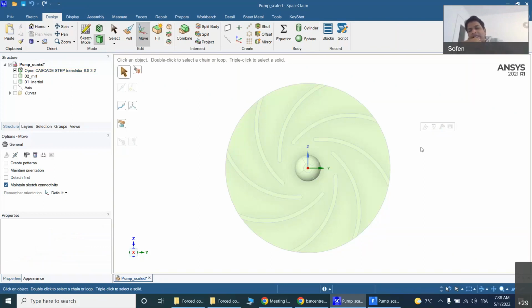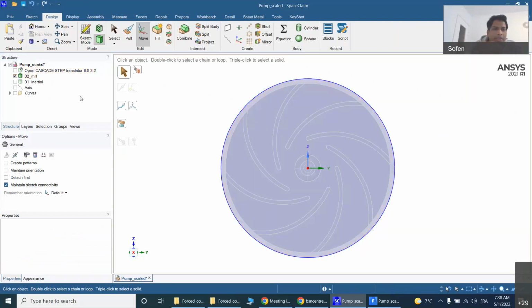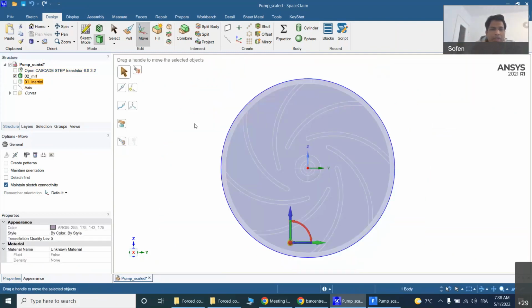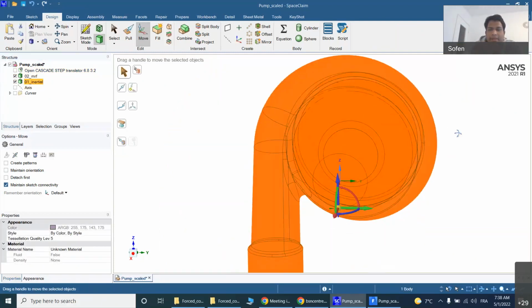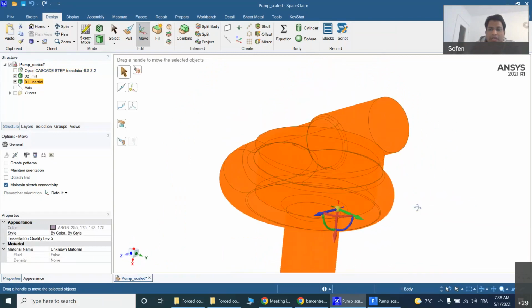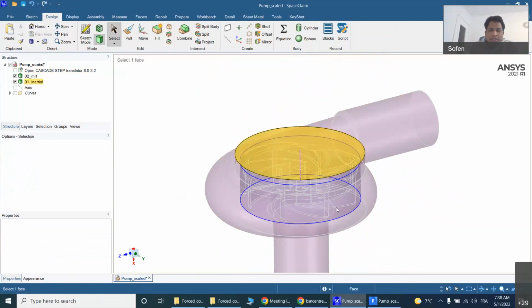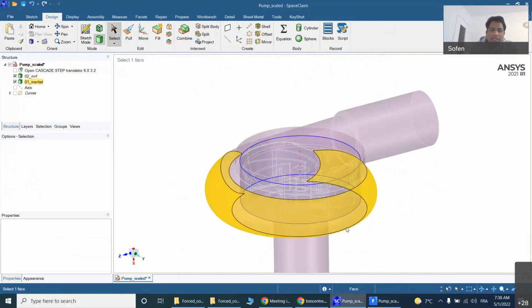And when it slides, a non-conformal interface is created, right? When we go over here, the MRF zone between this and this, as the zone moves, the non-conformal interface will be generated. The blue region you are seeing, the non-conformal meshes will be generated over here. That is called the sliding mesh approach.